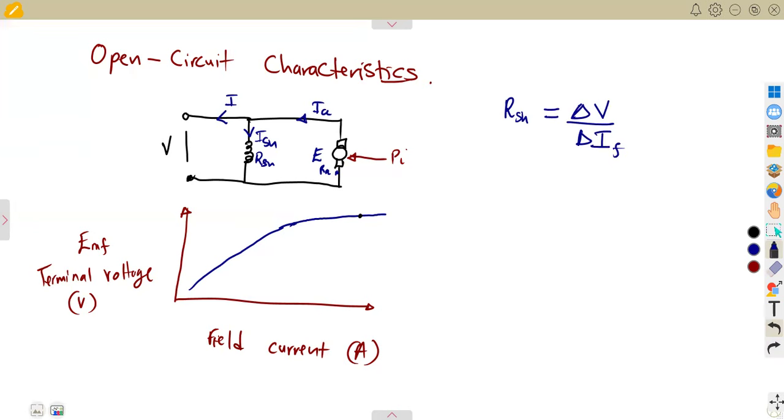Guys, let us go back to our mathematics. The change in voltage over the change in current is actually representing the slope, the gradient. Remember from the gradient concept, the change in y over the change in x. Y is representing the EMF, X the current. So from the resistance that you are given, you are taking that as your gradient.